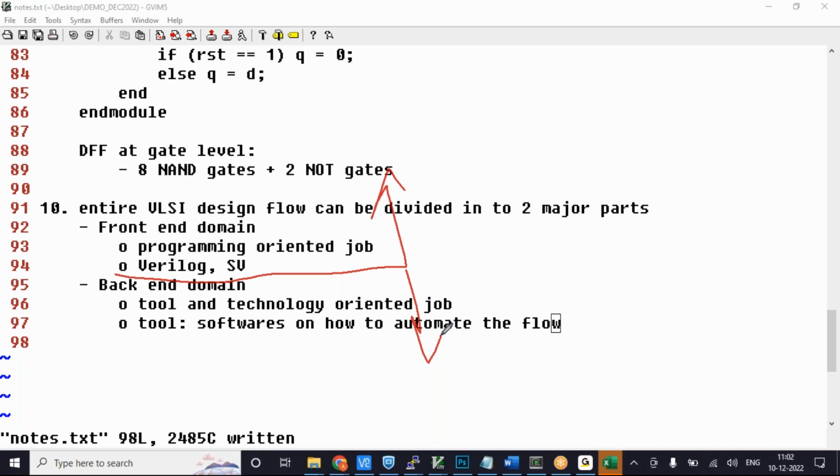I'll give you an example. IR drop analysis is important. Don't you think it's important? Let's say you construct a very big house, and finally you see that the lights are not glowing properly and your heaters are not working. Will there be any use of such a house? No, right? Then what should you do? You should call an electrician and ask where the drop is happening, why the voltage is not coming properly. The problem in chips is that you cannot do that once it has been manufactured. Once manufactured, done. So it has to be checked at each stage, has it been done properly?